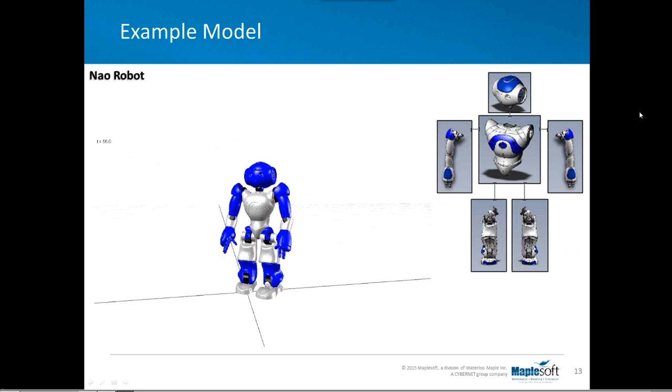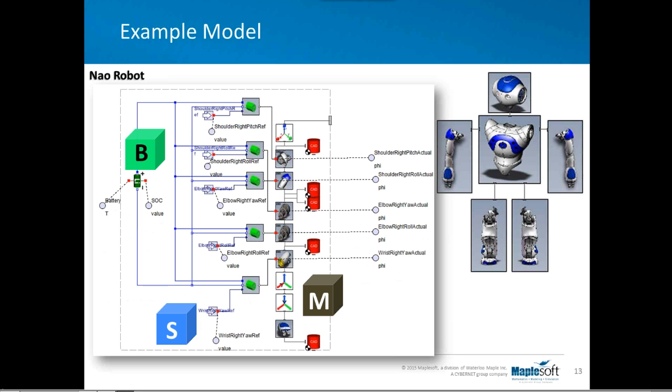It could be platformed to do some interesting dynamic analysis of different types of motion. But what we are able to do in MapleSim is go beyond having the dynamics of the system and the multibody part. We can look at more detailed subsystems in the same environment, all in one. So here we are focusing on one of the arms. We can see that there's a string of subsystems that represent the joints, the inertias, and also actuations. In this subsystem, we have multibody and 1D rotational. The connection from the servo actuator to the joint is through a 1D rotational domain.